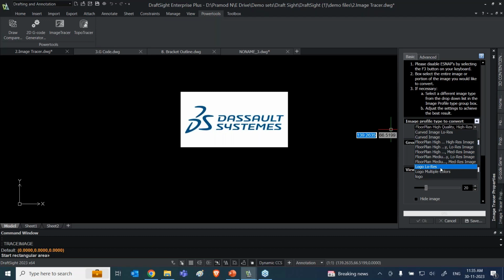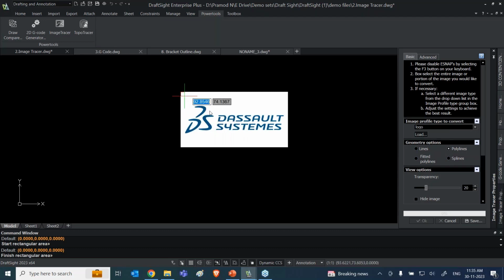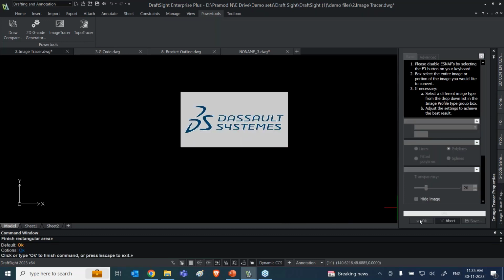So based on the case study you are working on, you can select the options over here. As it is a logo that I'm going to extract, I'll select the logo. And the next thing is in which format I want to extract data from this: whether lines, polylines, fitted polylines, or splines. I can select the options over here. And once everything is done, I shall select the image with respect to which I want to extract the data. Now that I have selected the image, I'll just click on OK.